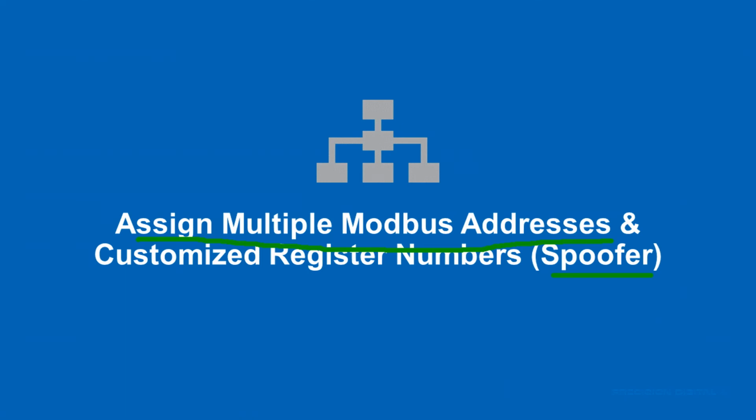And then you can have it respond with customized register numbers. So in my example I just gave, my default address, so to speak, my standard address that I programmed into my consolidator was 100. And so if I want to pull out any of my process variables, the states of my relays, figure out how it's programmed, I can pull all that out based on the lookup table in the Consolidator Plus manual. And it will tell me, great, if I call Modbus address 100, and if I ask for register 0, I'm getting PV1.